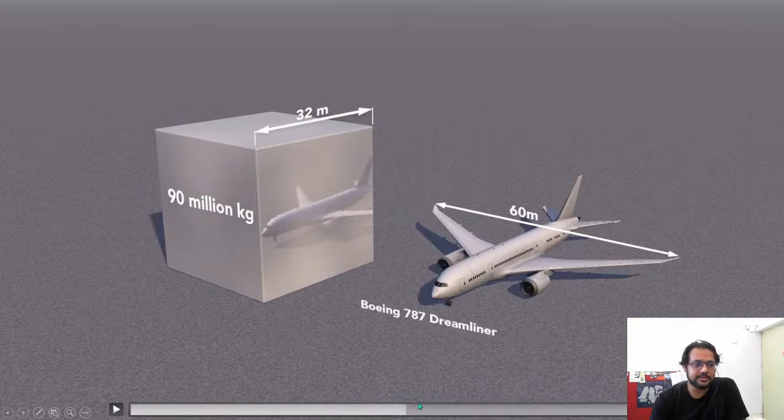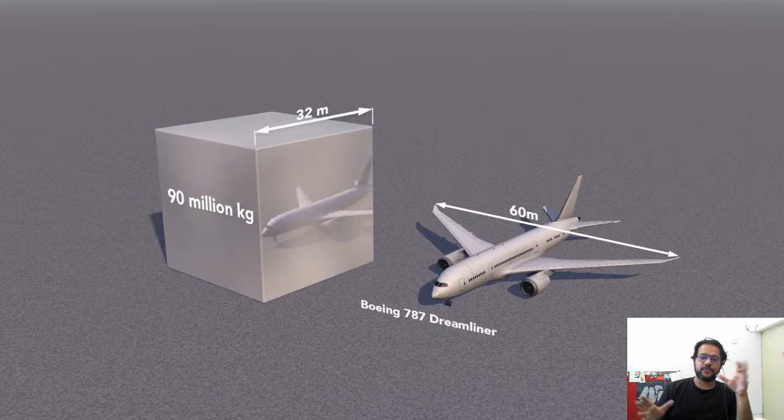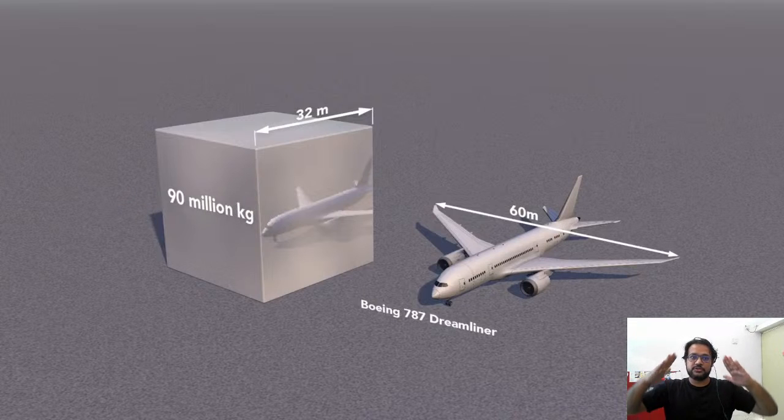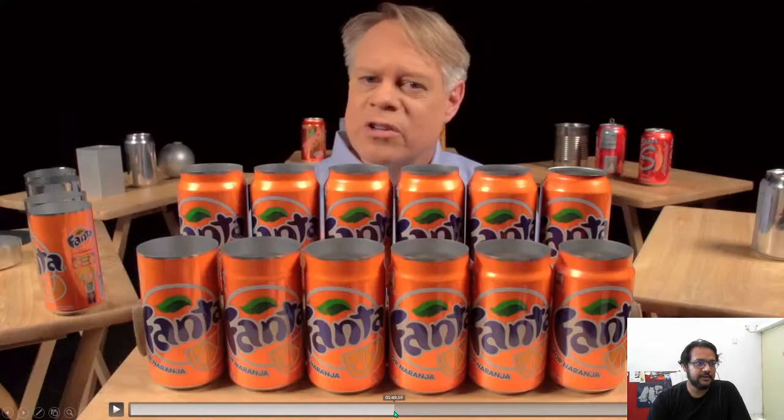So the neck drawing operation, if you saw clearly, is only done towards the top part of the can. It's not done at the bottom. That means the sides of the can are fairly protected during these operations. I think if you did it the other way around, you would not have a decoration which curves, like for example, if you see in the video, the decorations are part of this curve also. If you had already done the necking operations and then gone for decoration, you would not get the designs in these curved parts very effectively. Okay, so that's the idea.